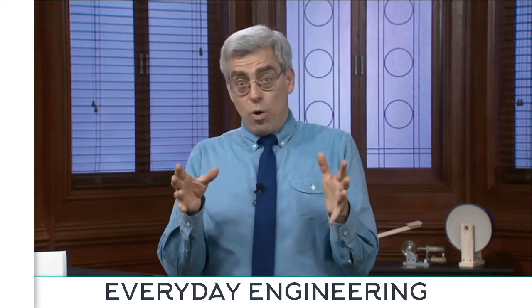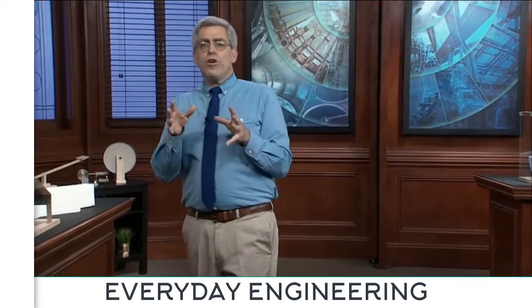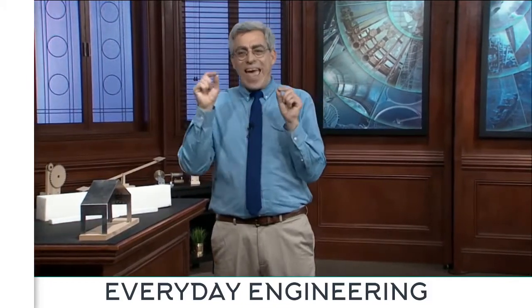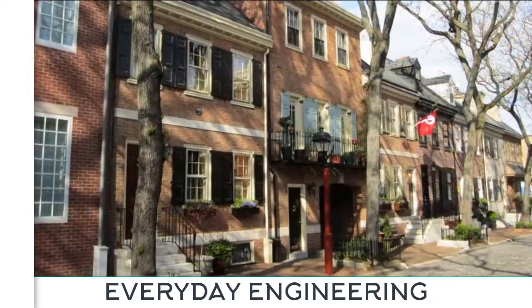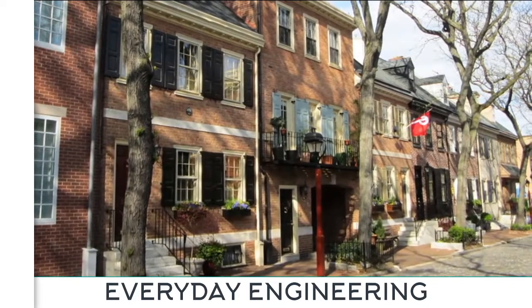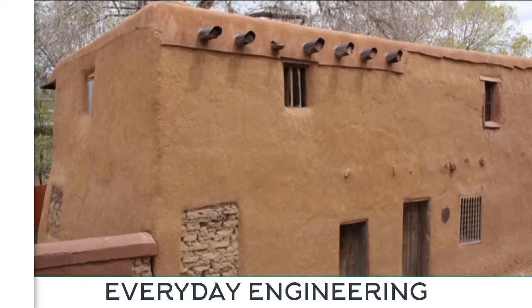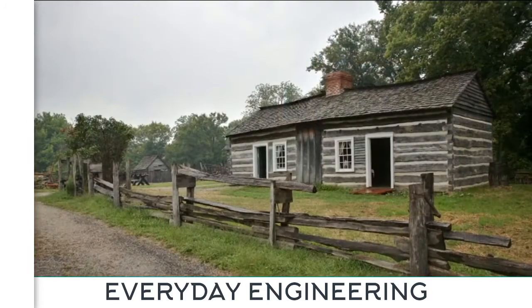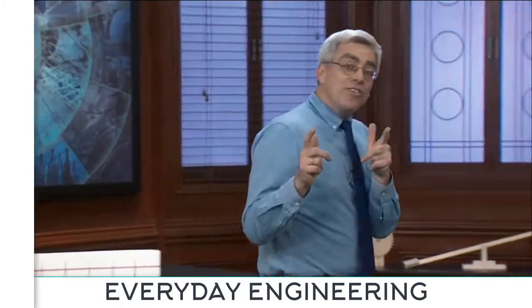In the U.S., bearing wall buildings dominated residential construction throughout the colonial era and well into the 19th century. In a bearing wall structural system, the principal vertical load-carrying elements are the building's exterior walls, which are typically made of solid stone, as in this 19th century farmhouse, solid brick, as in these colonial-era townhouses, mud brick or adobe, as in this pueblo in the American Southwest, or solid wood, as in this log cabin. And here's how the system works.